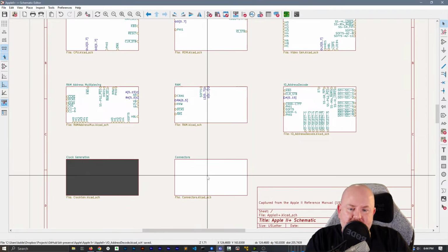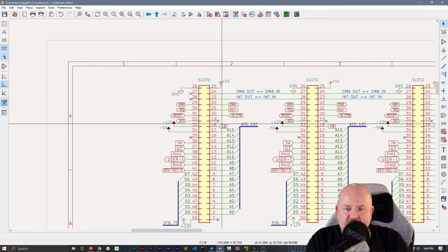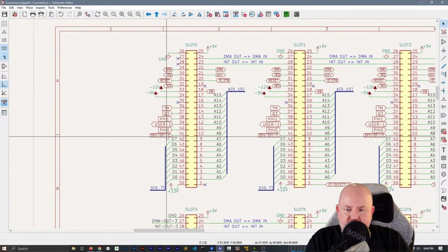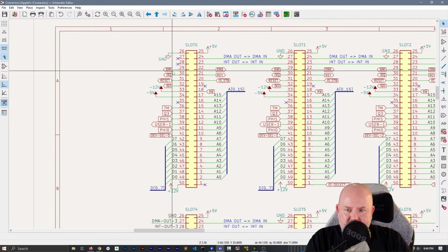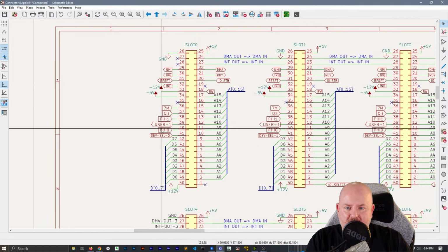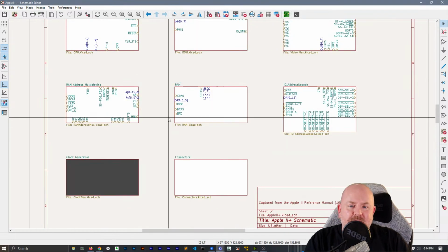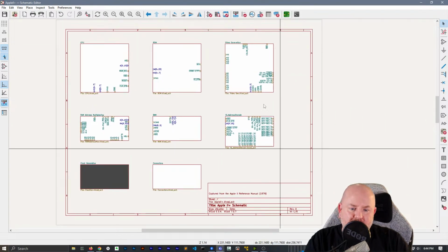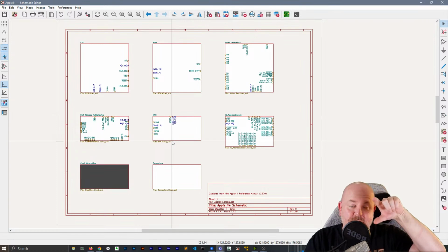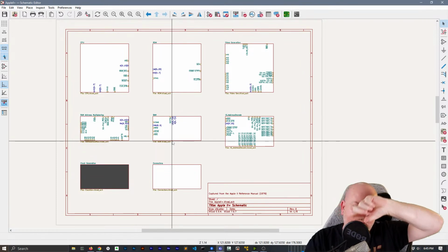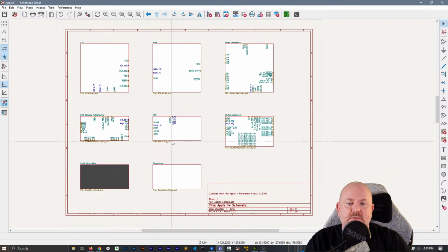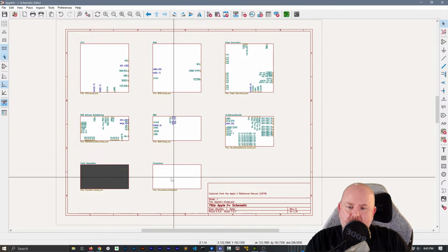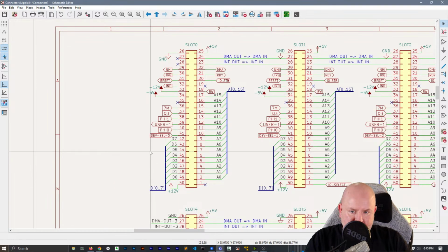And then the next mistake is, for example, you can tell on this page, they used global labels instead of hierarchy labels. I like having the top page on these, especially on these vintage computer schematics, with the lines between the blocks because it's much easier to see how subsystems are connected together.